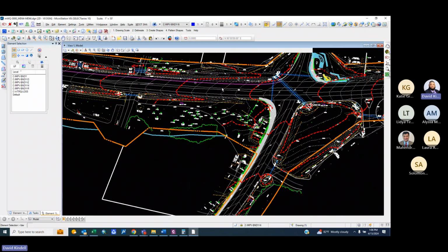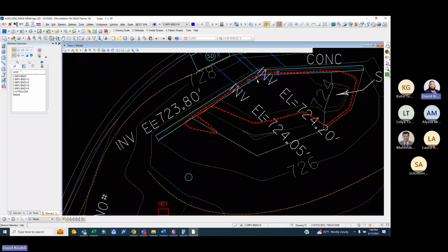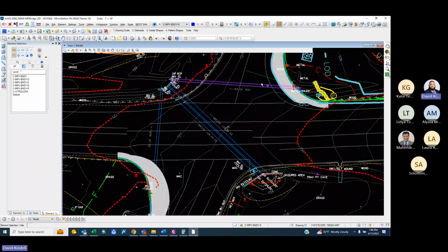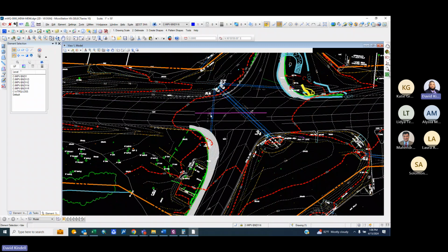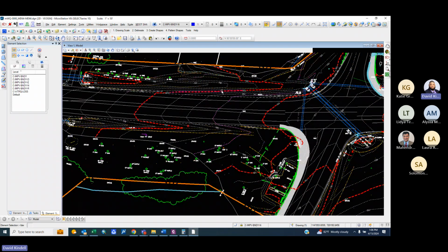So we can safely assume you have area coming to the cover here, and here, and here, all going to here. And it's pretty fair to assume this is more than 1 acre. So it's not feasible, or it doesn't make sense, to put a bioswale here.